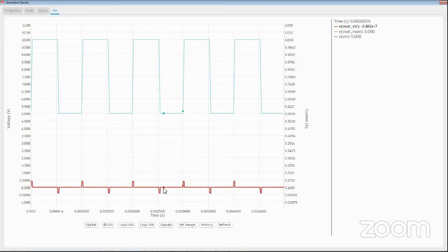And the idea of showing you these low frequency examples is that because in many designs you're not dealing with hundreds of megahertz or gigahertz, you don't run into these types of effects, even though they're there, even though those intrinsic capacitors are there, those intrinsic inductors are there. At low frequencies, they're transparent. They don't really change things much.